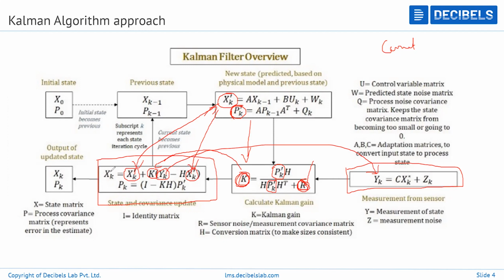Okay. Whatever you get from this particular block, you can take as the final output, or if you have further estimations, we can make use of them as the previous state. The present state updated values, that is x of k and p of k, can act as the previous state for the next predict step calculation or estimation.